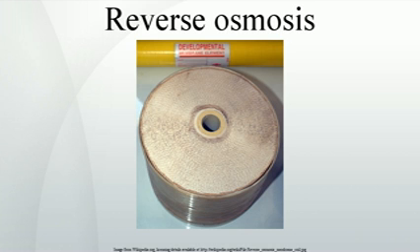Remineralization and pH adjustment. The desalinated water is stabilized to protect downstream pipelines and storages, usually by adding lime or caustic to prevent corrosion of concrete lined surfaces. Liming material is used to adjust pH between 6.8 and 8.1 to meet the potable water specifications, primarily for effective disinfection and for corrosion control. Remineralization may be needed to replace minerals removed from the water by desalination.